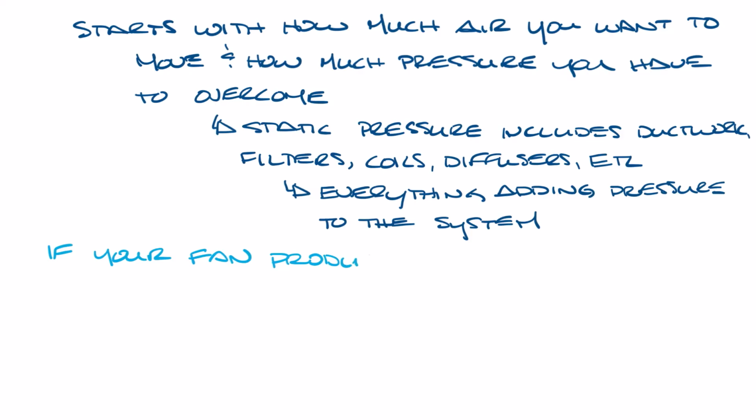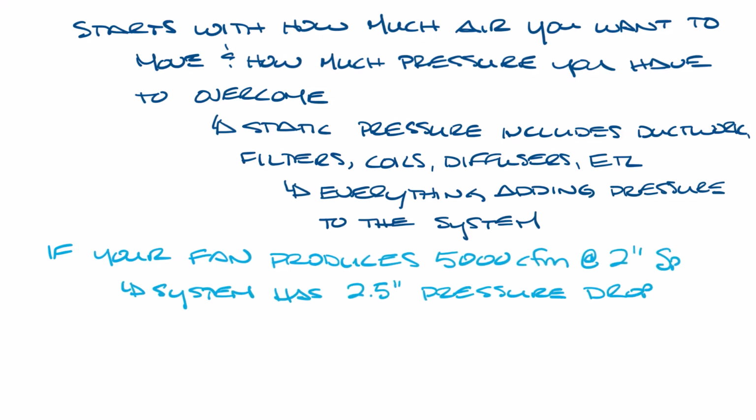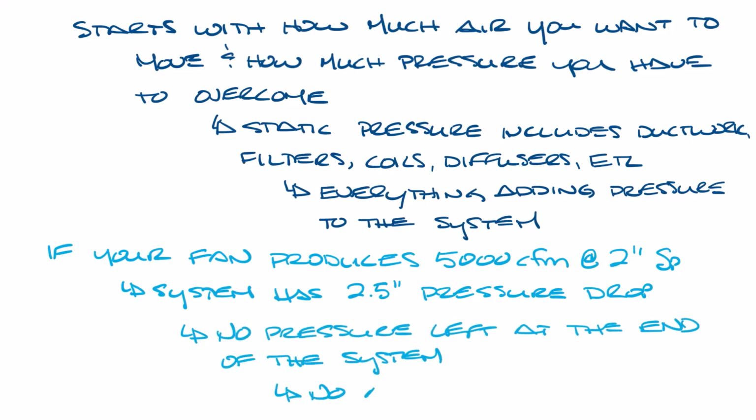If your fan produces 5,000 CFM at 2 inches, but your system has a pressure drop of 2.5 inches, you basically have no pressure left at the end of your system, meaning no airflow. So let's look at a fan curve.